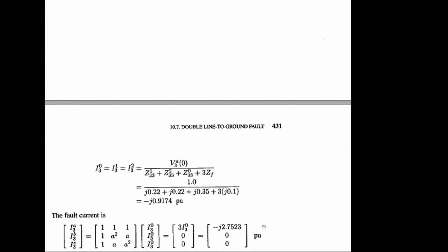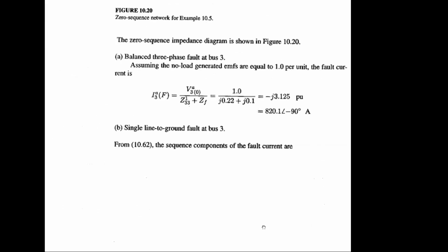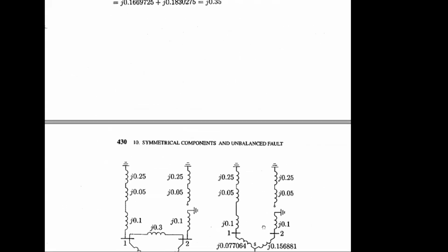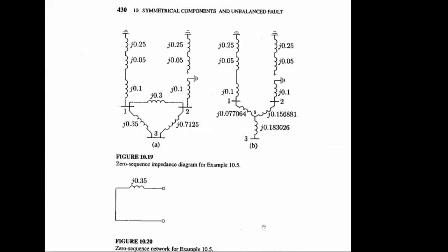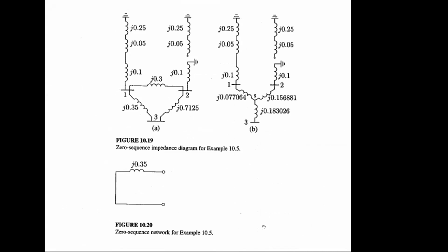Actually, this problem requires a two-step solution. First step is to generate the Thevenin equivalent impedance to address the different Z. Second step is to determine all the fault currents in terms of different configurations. That's the final, or total, picture of this problem.